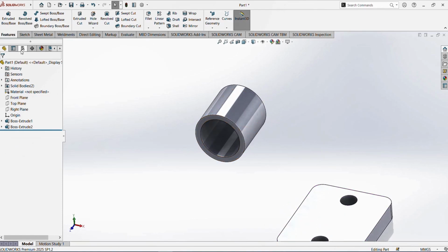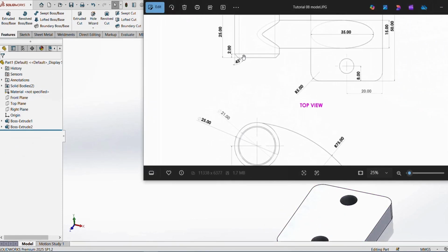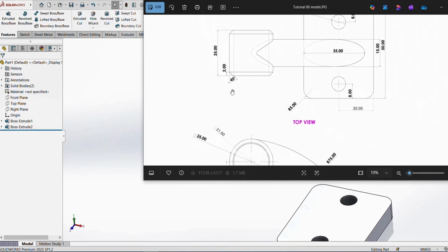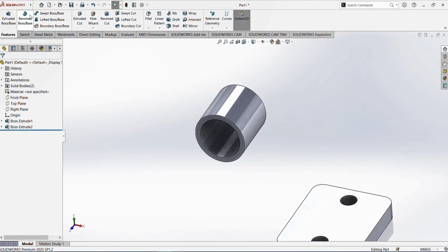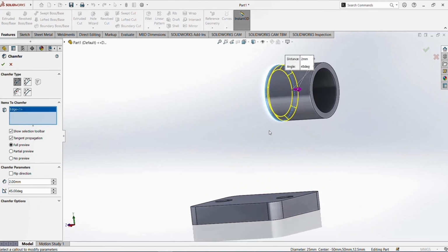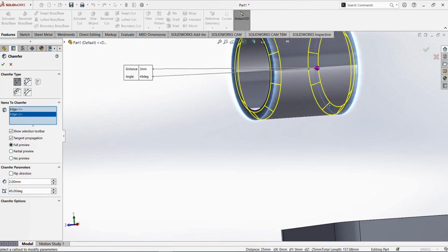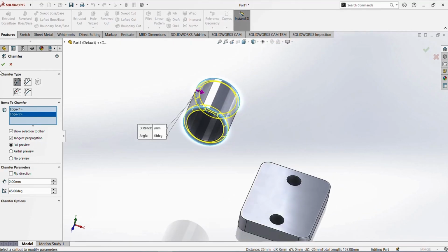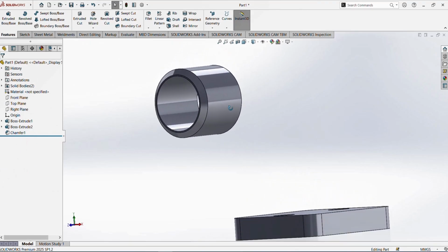Here apply the chamfers. Mention the chamfer parameters 2 and 45 degrees. In the features, here are the fillet options; select the downward arrow, chamfer, and provide the distance as well as the angle. Here I select the distance 2 millimeters and angle 45 degrees as it is, and select the edge where to apply the chamfer. I select both circular edges. Now the chamfer is applied.